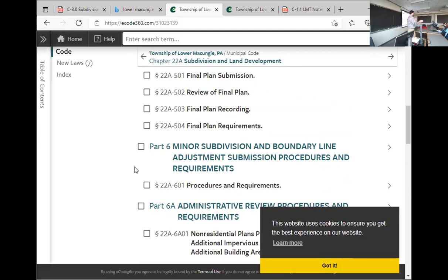Okay. So if you're going to submit it for a November planning commission, okay, that's the board that's going to review it, the planning commission. There's a deadline. It's usually 3 weeks, 30 days before the date of the meeting. So they have time to look at it and comment on it and what they like, what they didn't like. What do you need to negotiate and work out? You interpret the ordinance this way, their attorney or their engineer interprets it differently. Okay? Sometimes it's not always black and white.